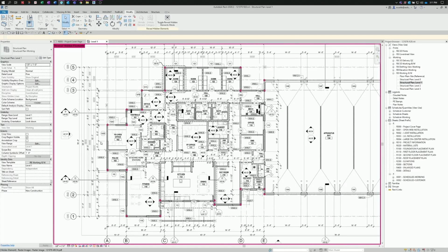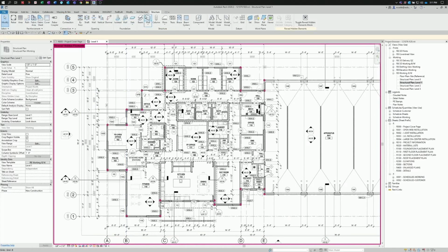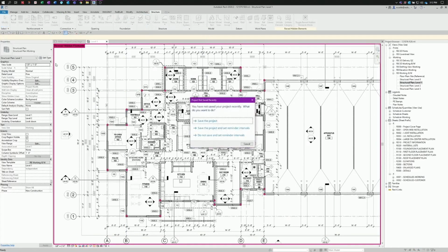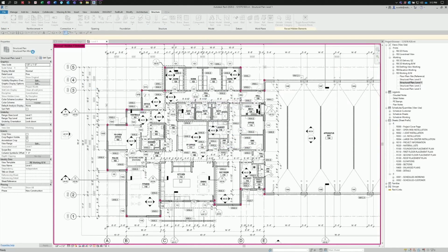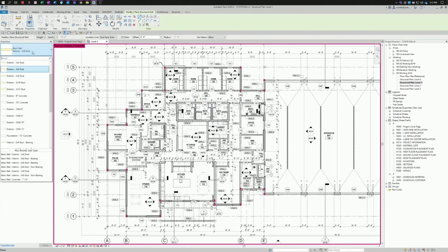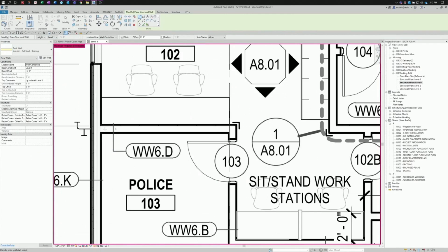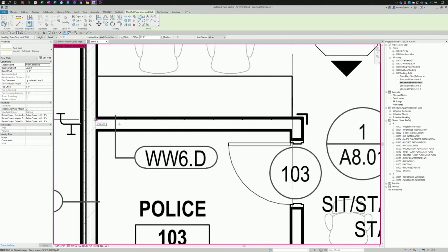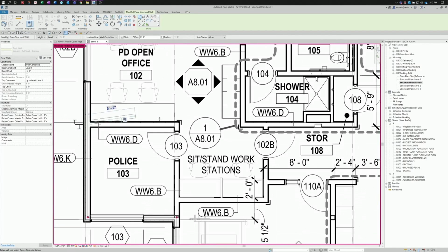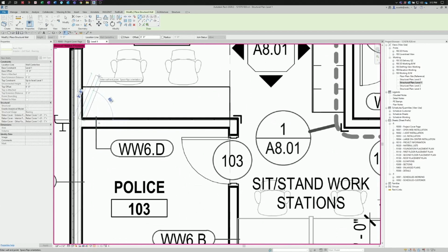Now to start interior bearing walls, we go back to structure and start our wall, save our project, and then pick the interior 2x6 bearing walls. And then come in, and again we're just going to be sketching as close as we can all the bearings.